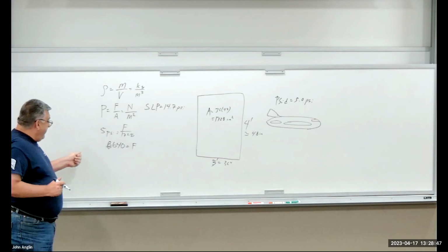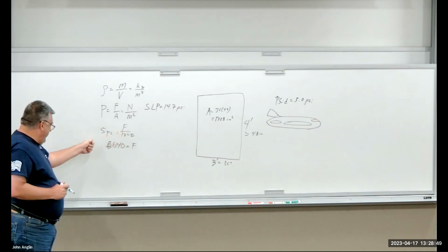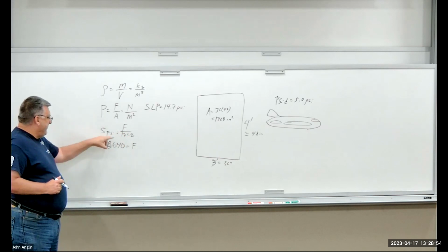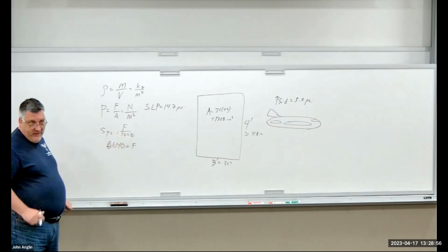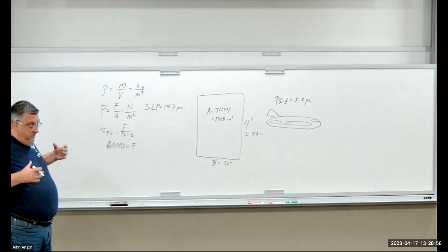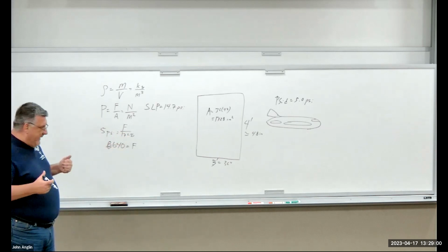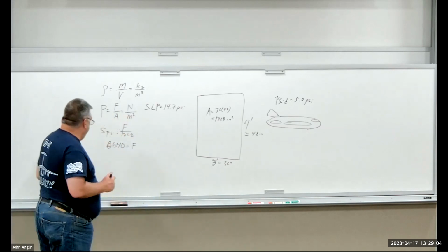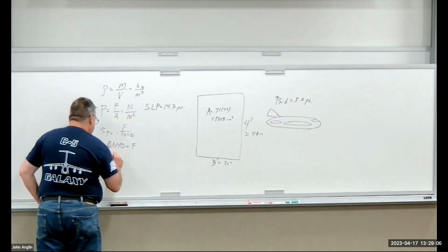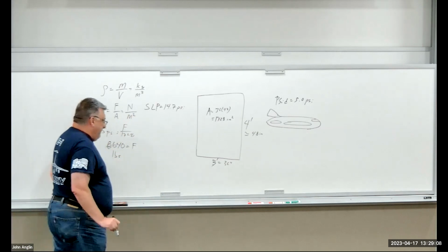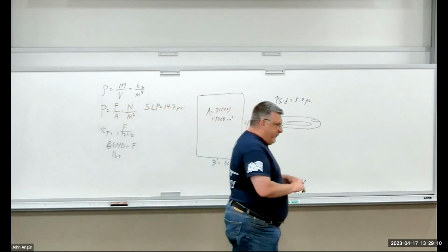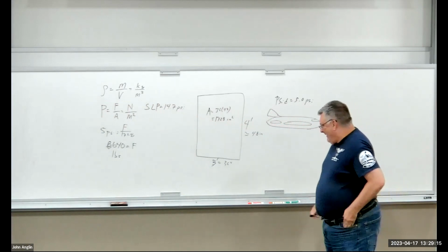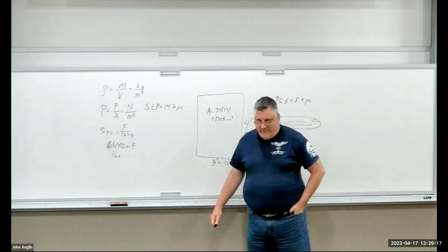What are the units? It's not newtons, because we use pounds per square inch for pressure and square inches for area. Because we're using that same unit base, we know our force is going to come out in pounds. So this is the amount of force you need to apply to open that door in flight: 8,640 pounds.